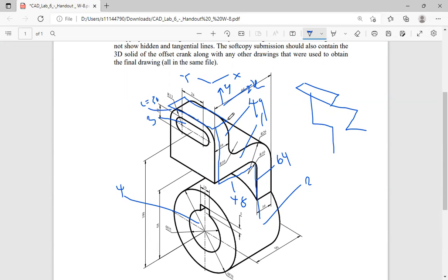What we're going to try and do is draw this surface, then draw the path. So 49 by 48 by 64 with that radius 10 in here. And then we're going to use the tool called sweep. So it'll just create a constant S shape.